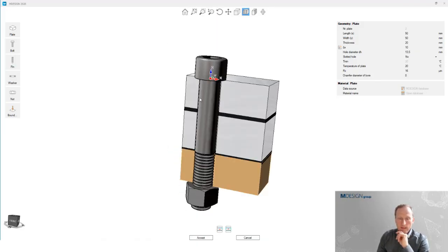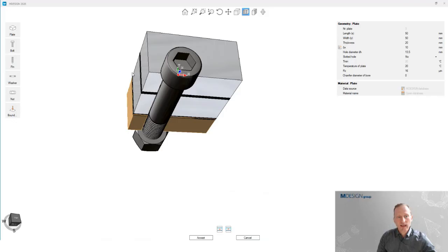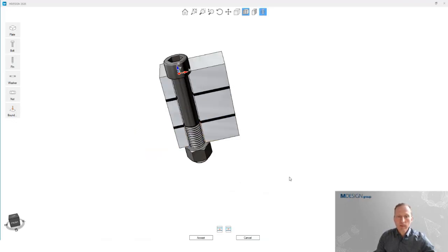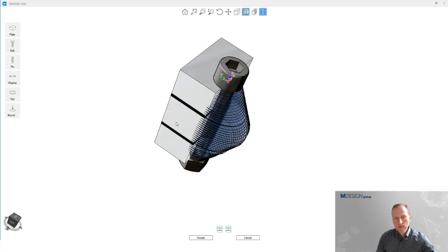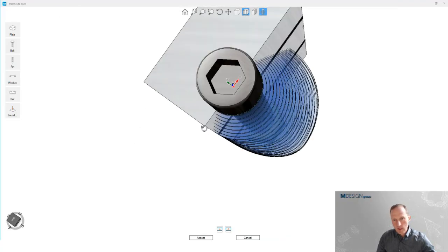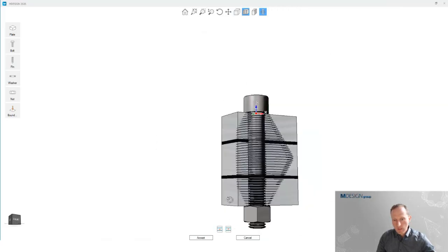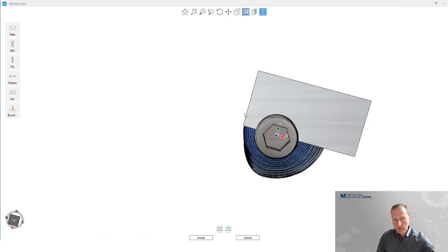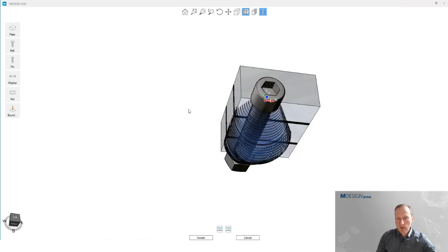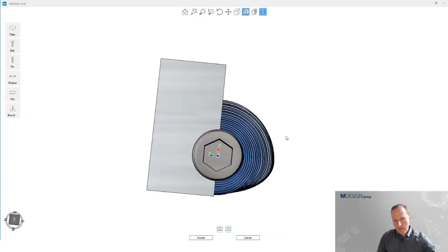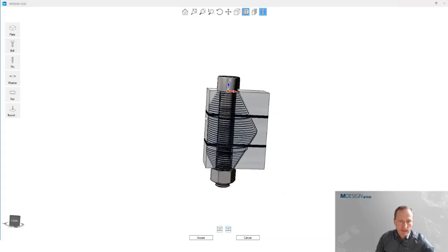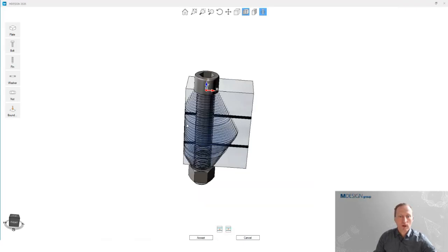So, okay. And in the first step now I can check, is there a cutting of the pressure cone? Therefore you see this icon, you can now create the clamping situation. You see now it used the integral approach to get this pressure body, and of course it's cut on the left side because the bolt is close to this side, and so we get a slightly elliptical pressure body, and the eccentricity will be calculated automatically from each part of the pressure cone.